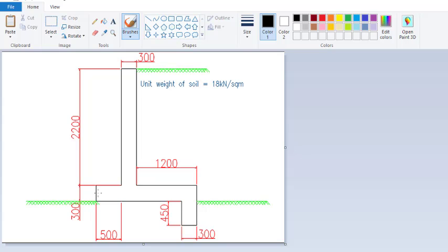All right, as far as you know in Staad Pro, before you can model any element, what you should be concerned about is the points, you'll be needing the nodes. Okay, so we need to know where we'll be having the nodes. So let me just depict the points that we need the nodes that will enable us to draw the model. Okay, so let me pick this. So at this point we'll be having a node.